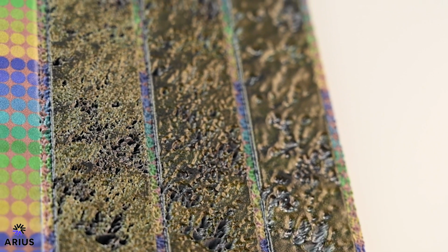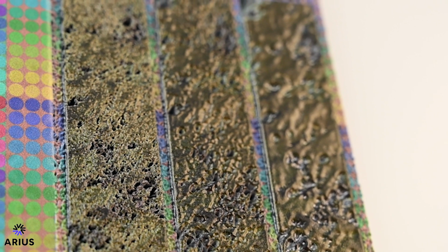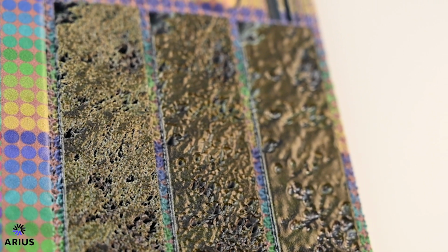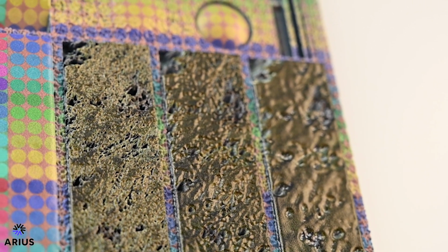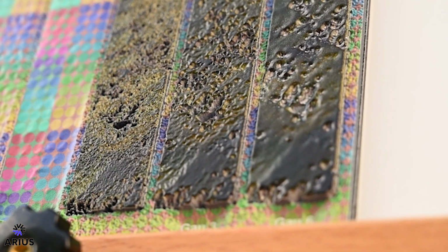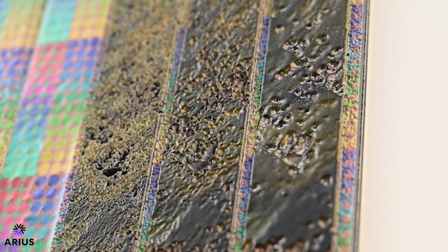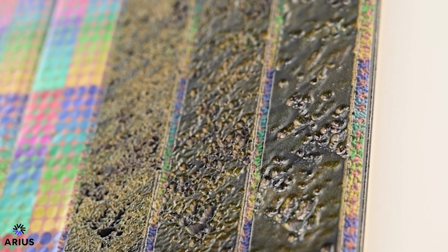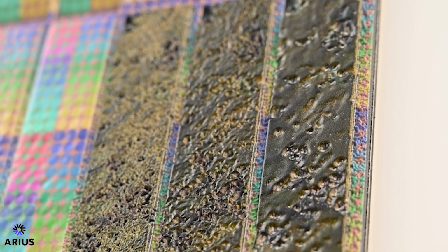The center sample has had the grayscale elevation map blurred with a Gaussian value of 3. The result is less noise, but still has dark crevices with little color ink on these slightly slanted walls. On the right, Gaussian is set to 6 pixels, and now we see some of the pale sky color beginning to show as the black walls are further smoothed, drawing some green pixels down and blue pixels up, revealing the sky. A higher setting will fully bring back the color in the crevices and the sky to the elevated image.